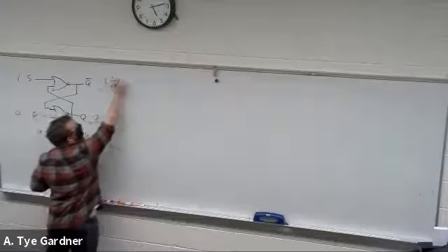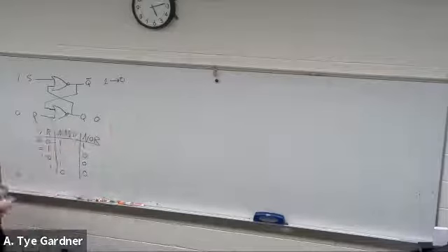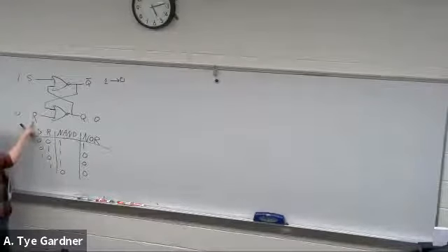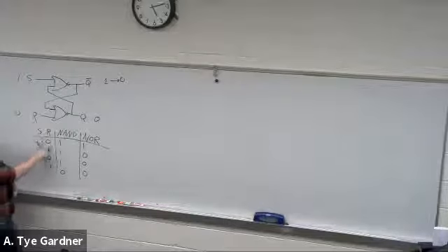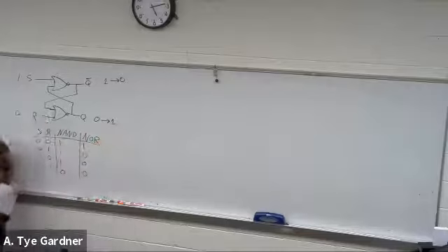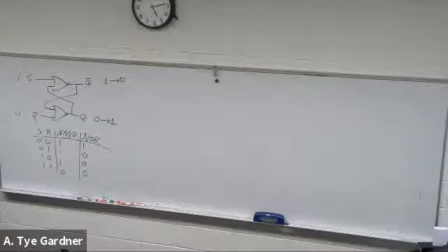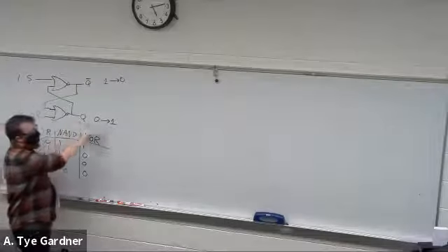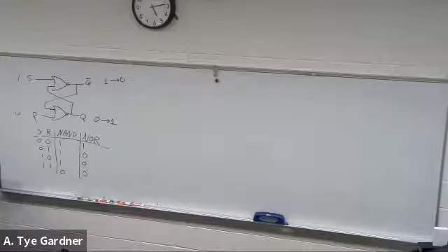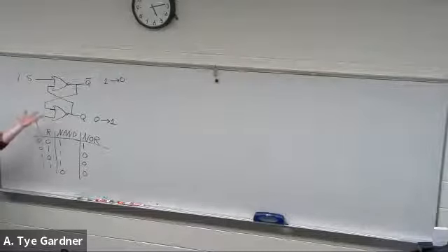So a transfer from 1 to 0, right? So that puts a 0 down here, a 0 still on the reset because I haven't changed that. And now I'm at 0, 0, which flips this to a 1. So that's what set does, set makes Q 1. Now this is actually true regardless of what the previous state was, which you could go and prove, but set just says, let's make it 1.